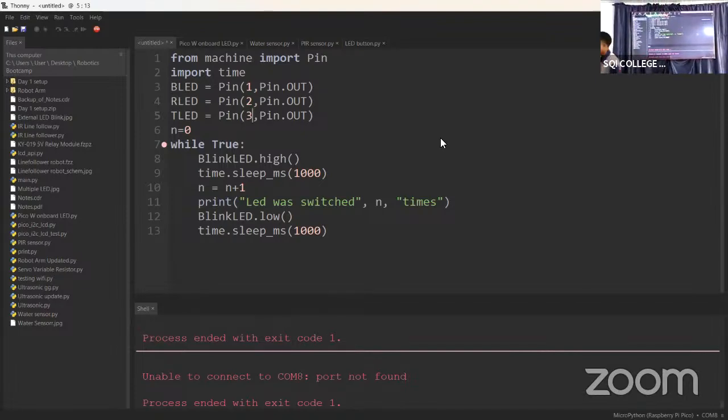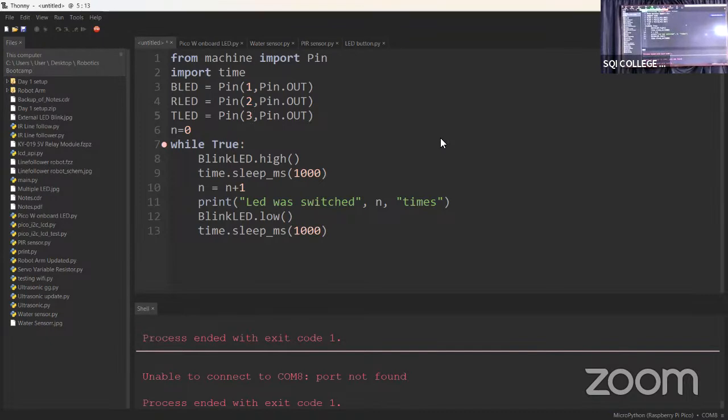I also mentioned something: I think 26 is an analog pin. Check. Pin 26 has an A following it, probably like A0. You can use it, but maybe use a pin different from that, because you might have issues with that pin. Pick something that doesn't have A0 at the back, then update it here. If I'm moving 26 to another number? 20.